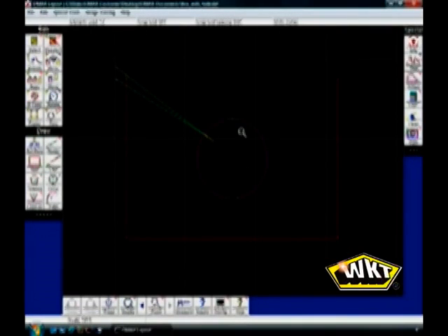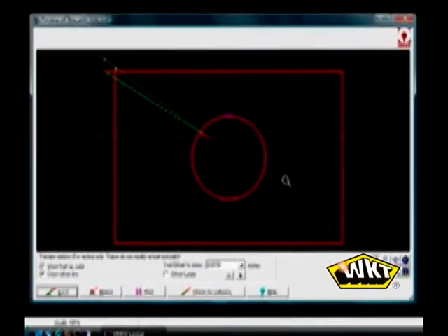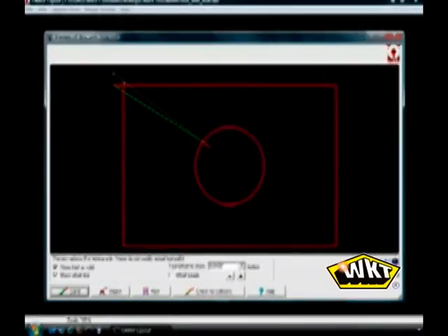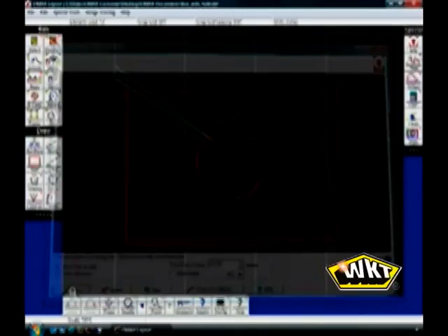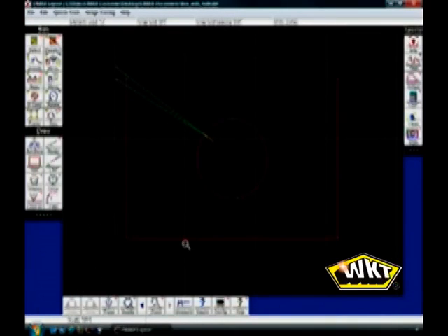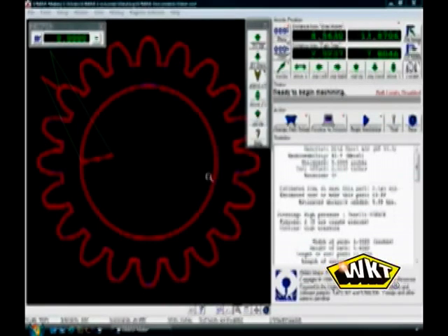Now that's saved. The next step is to take this DXF file and turn it into an actual toolpath file. And that's done with this path command here. I can preview it here with some arrows to see the direction things are going and so forth. And if everything is to my liking, I can save this. So I'll save that, and now we're ready to use OMAX Make to actually cut this part. This is OMAX Make, and its purpose is to position the machine, and of course to run tool paths and cut parts out.